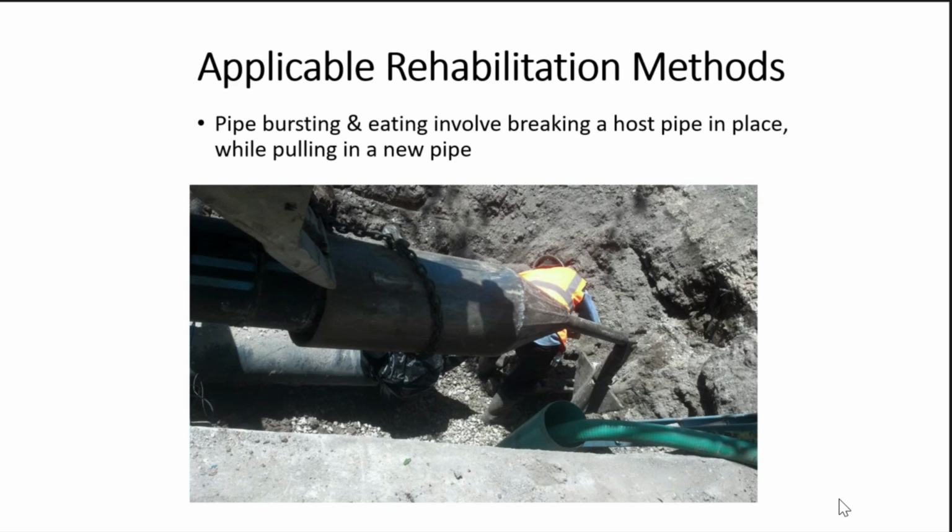When we talk about techniques, the first one that Ray talked about using on sewer was actually developed for pressure pipe. He mentioned it for British Gas, and it's used quite commonly for repairing small diameter pressure pipes. You can go in, and as Ray showed, you can break up the old pipe and pull in a new pipe at the same time, typically some type of thermoplastic pipe, PVC or HDPE, but you can use other materials as well.